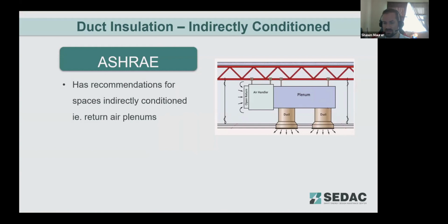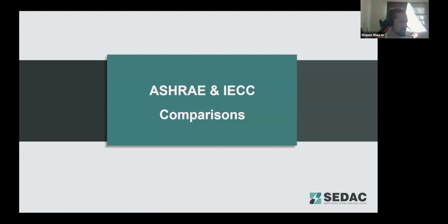As we noted, we've come across several locations where that insulation is not installed, following the IECC, where that space is considered a fully conditioned space. And due to duct leaks or outdoor air leakage into that plenum space, then you end up with condensation. And then you've got maintenance people looking for roof leaks that aren't there because the ceiling tile keeps getting wet, but it's coming off the ductwork. So that's the last of the ASHRAE specific requirements.